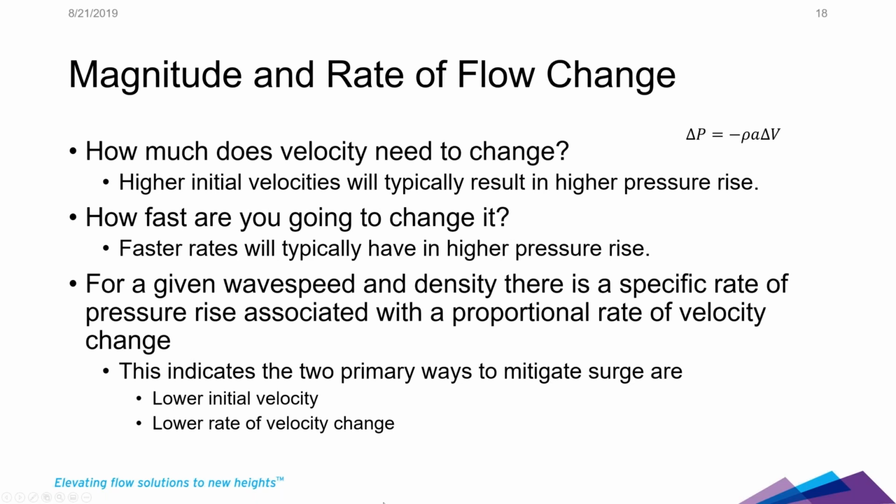Let's talk about magnitude and the rate of flow change. Whenever you start a surge analysis, think about how much does my velocity need to change? Higher initial velocities will typically result in a higher pressure rise. How fast are you going to change it? Faster rates will typically have higher pressure rise. So those kind of go hand in hand.